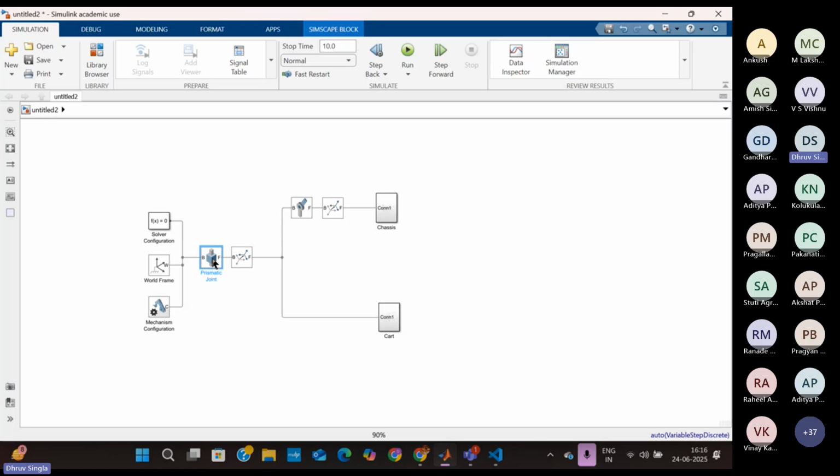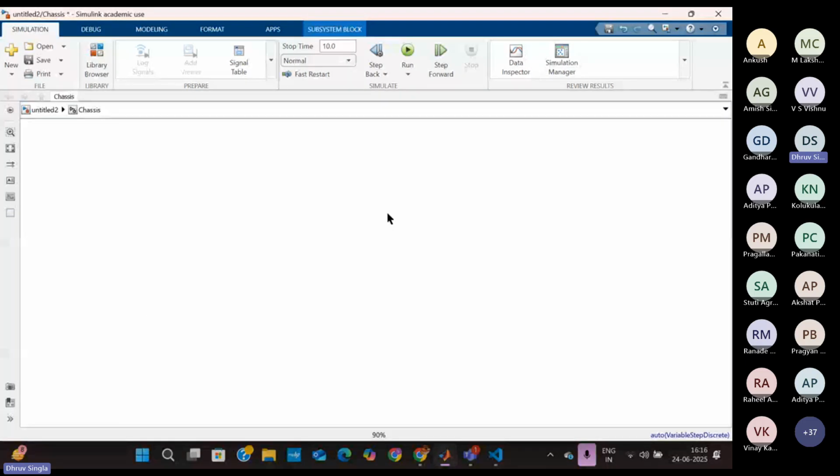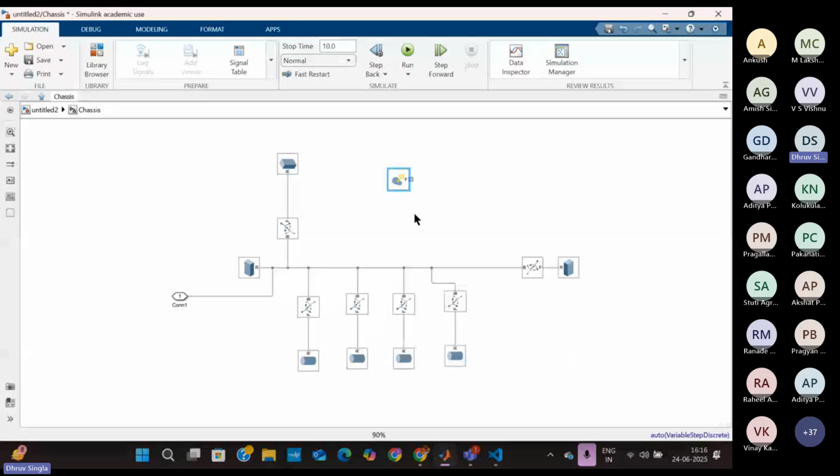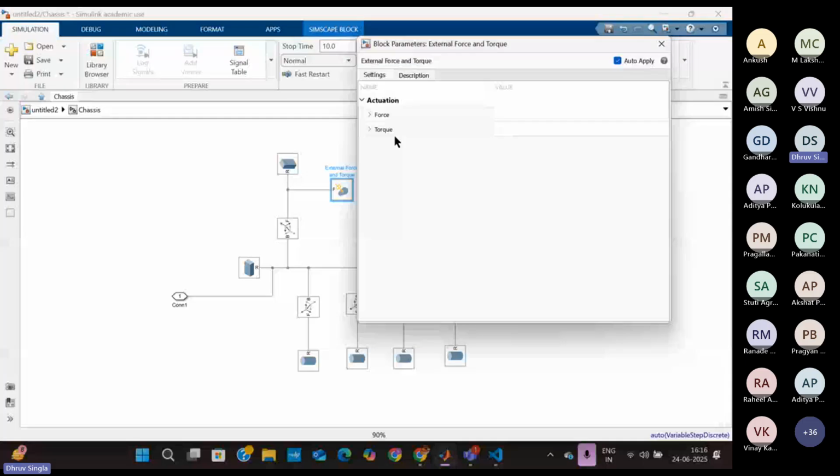So now this is how our board looks, and it looks like we have completed our board completely. So let us check how it looks if we apply some external force to it. I import another block, it says External Force and Torque, this block. I rotate it again and connect it to the third plate. I'm applying the force to the third plate, the topmost plate of my board, and I double click it. I want the force to be applied in the y direction, and I give the force a step function. I import a step function out here.